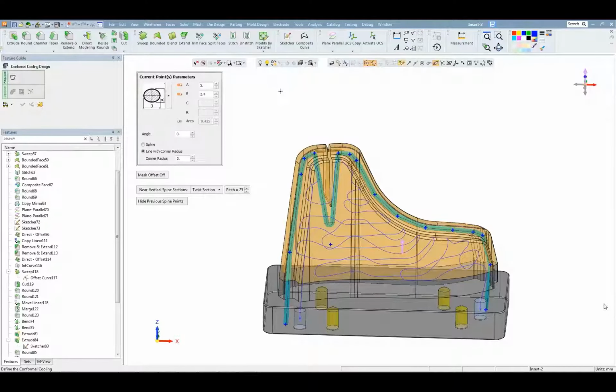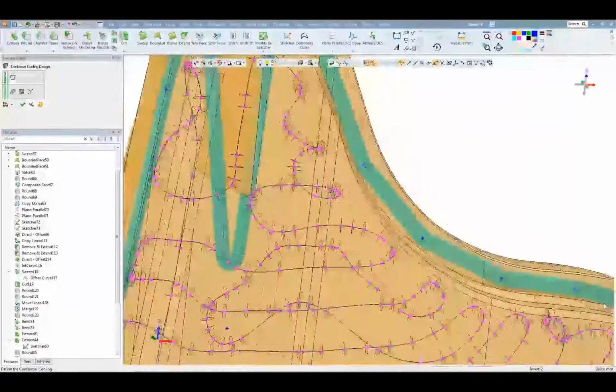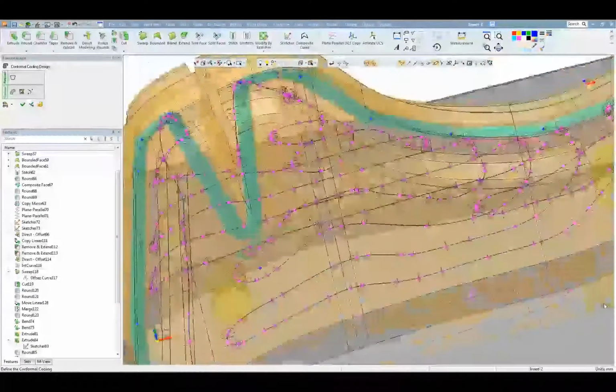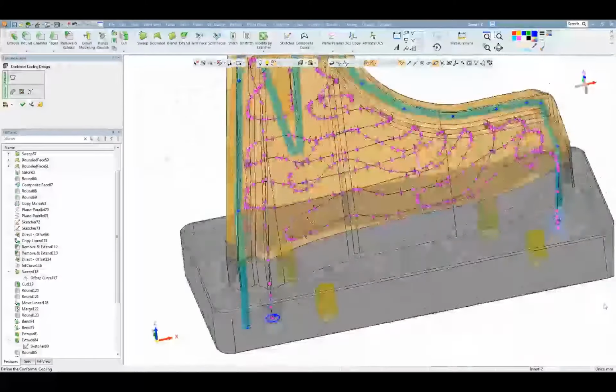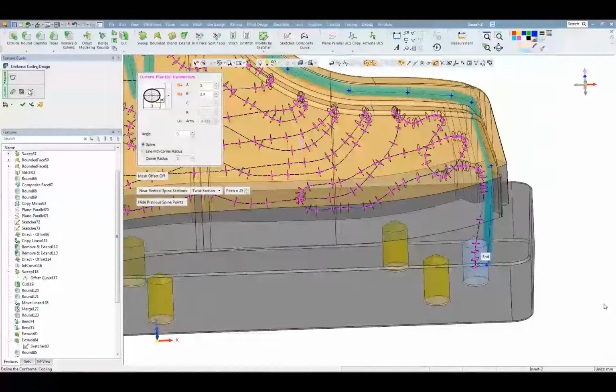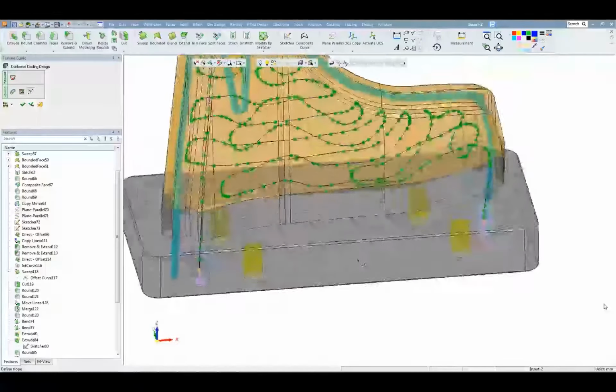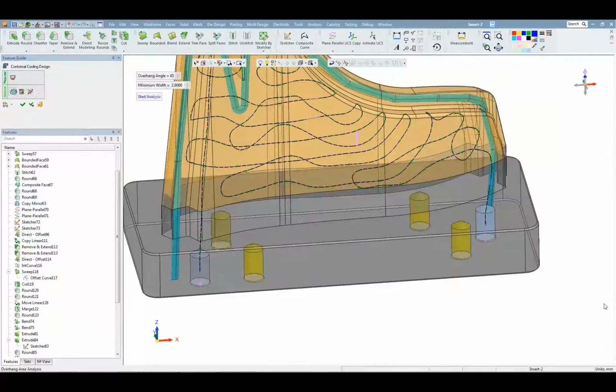Again, coming back to the conformal cooling design tool, we can now select this spline geometry for creating the channel. You can see that we've got all of the control over position still with this complex spline curve being created. We are able to check the curvature of this spline tool. We can check the closeness to the wall. So because we have already defined a 4 mm gap from the wall, we should be well within the tolerance of what we've set within the analysis tool.